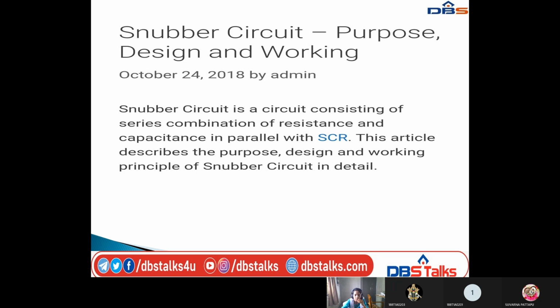The snubber circuit's purpose, design and working we have to study. A snubber circuit is a circuit consisting of a series combination of resistance and capacitance in parallel with the SCR. This article describes the purpose, design and working principle of the snubber circuit in detail.